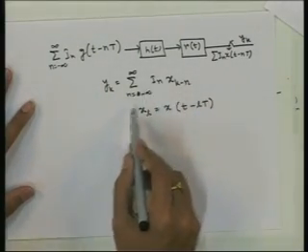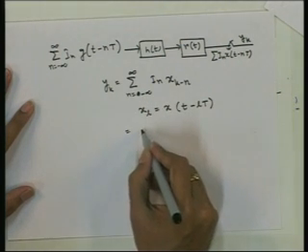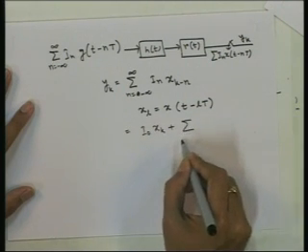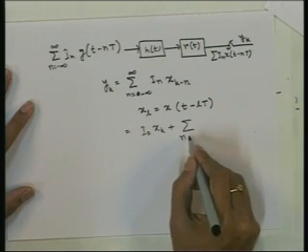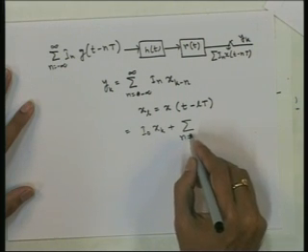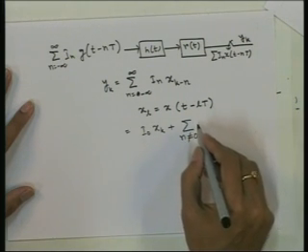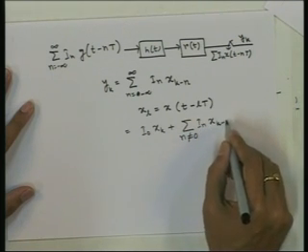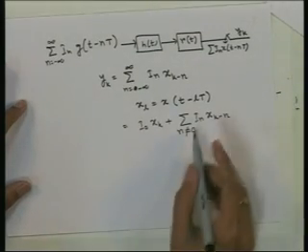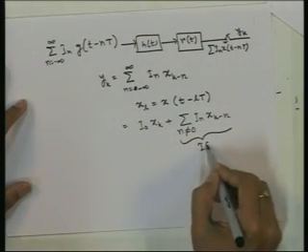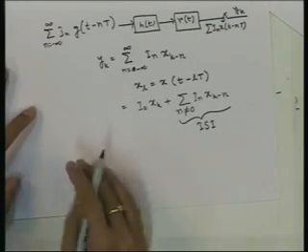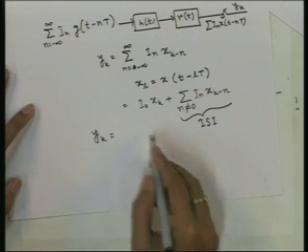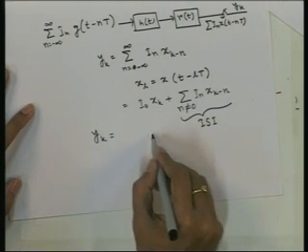So, this is basically I 0 x k plus summation n not equal to 0 I n x k minus n. So, this is the ISI part. Okay. So, this actually y k will be this plus noise.